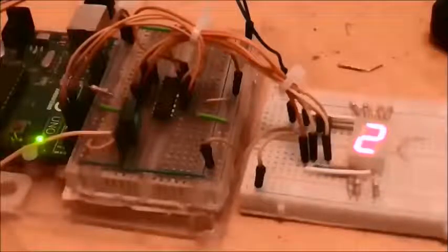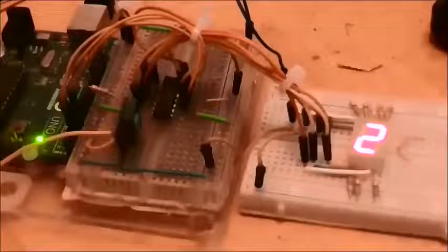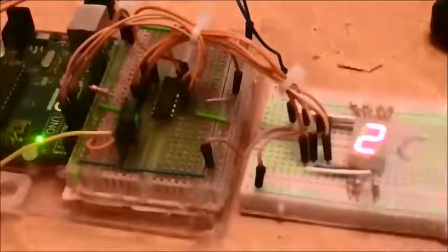So that's really the shift register, or at least it's the serial in parallel out shift register. You can get others. You can get the PIPO, parallel in, parallel out, and you can get the PISO, parallel in, serial out, and the one you'll see most often is this one, the serial in, parallel out shift register. And you always have to put data in with the clock pulse and then reset the latch to get the data to process to do whatever you want.